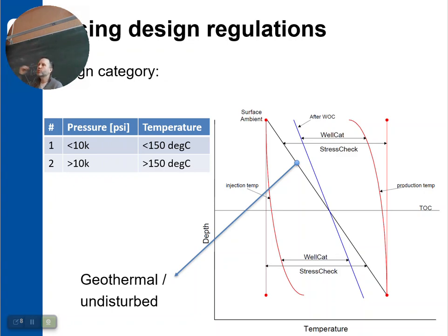When you start to produce, you're going to heat up your B annulus. Whatever fluid's there, it's going to follow that rule of thumb that I talked about, 1 bar per degree, right? So you have the difference here between the real produced temperature and whatever your base case was.